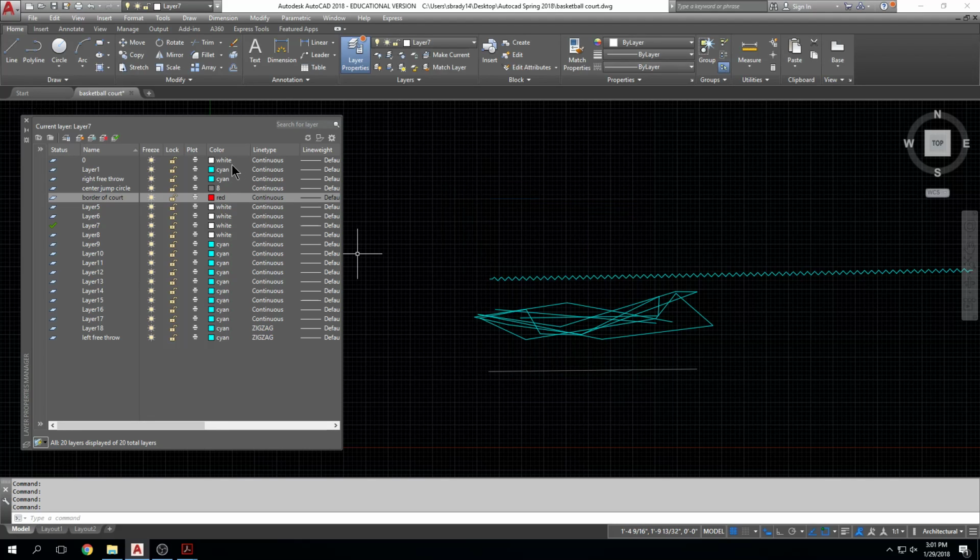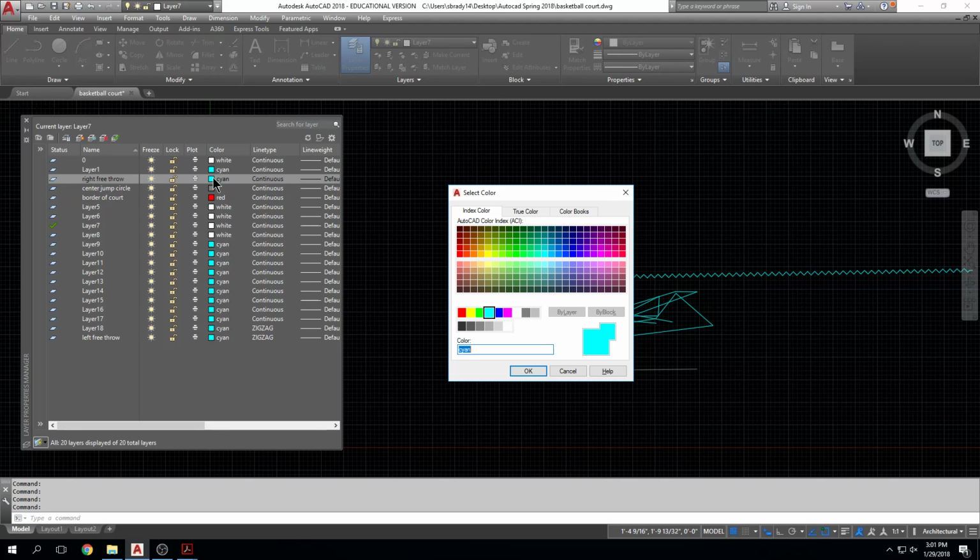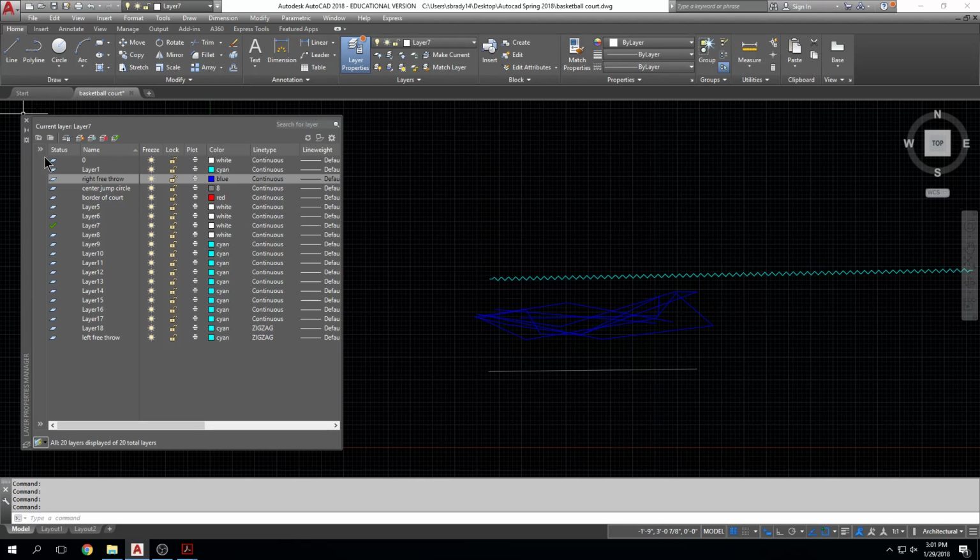Okay. Oh, well, that's it. Do not dimension the drawing and assign different colors to each layer. Well, I guess we have 2 of the same color. We could maybe make one different than the other, but very close. We'll do blue. Okay. So now I have my different layers created, and I have the different colors associated with those layers, right?